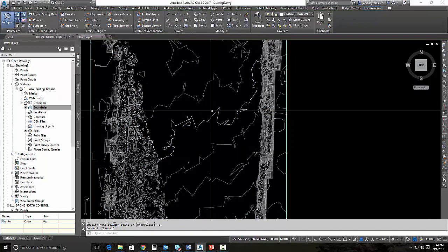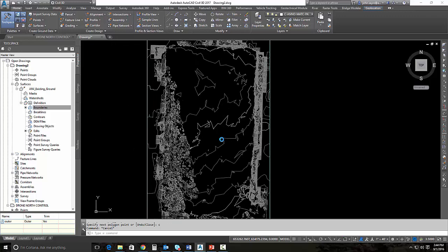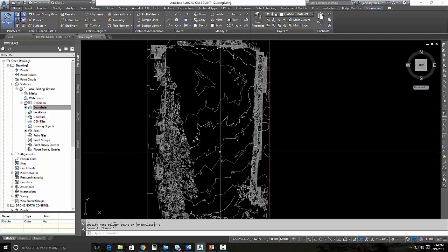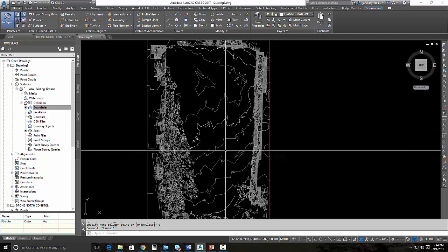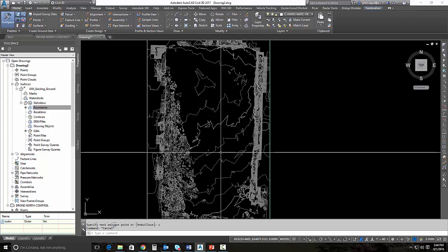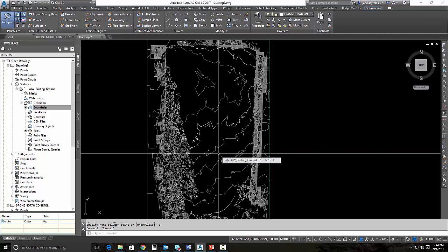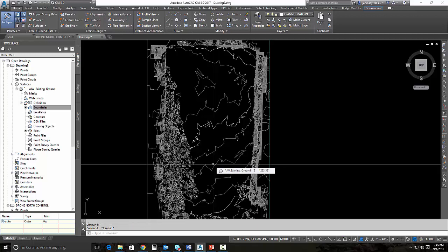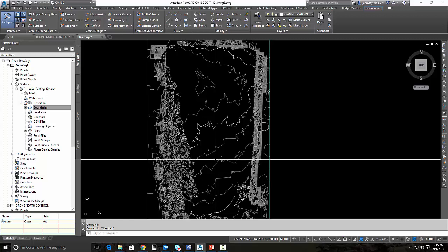We still have some jagged edges, but again, remember, we're using this surface for preliminary design, and this will be much better than any DEM information or anything like that that's presented by USGS. We can actually do takeoffs from this information to give people an idea as to how much money they're going to spend on the project. And sometimes you have to do that so that we can win work. With a little bit of tweaking, we can bring that surface in from InfraWorks 360, and we can generate a nice surface for preliminary design inside of Civil 3D.